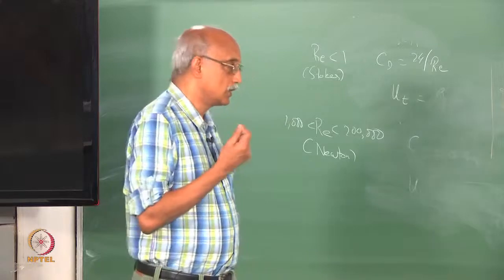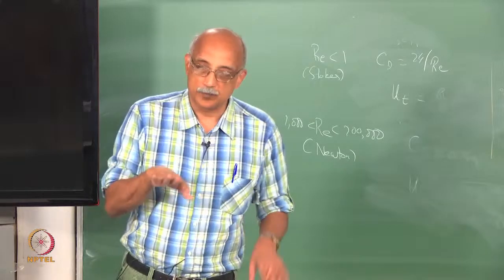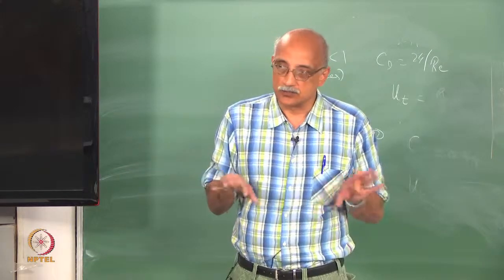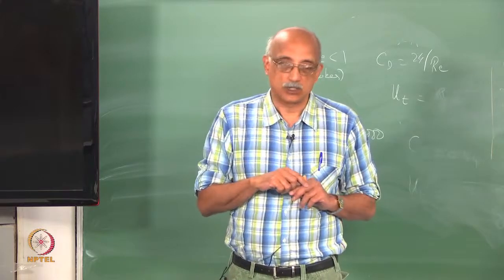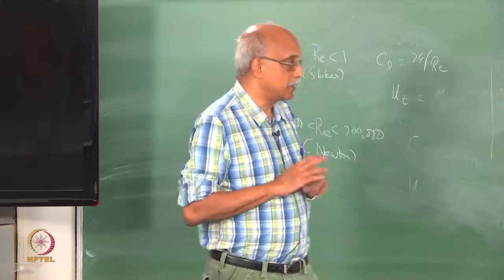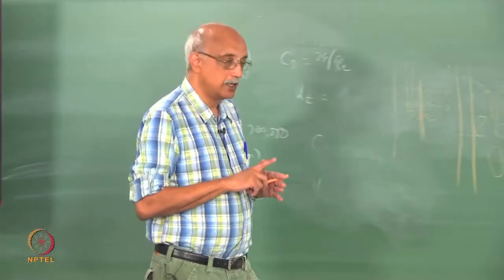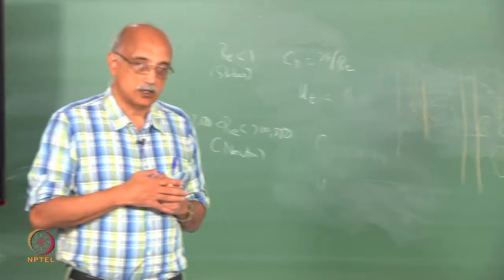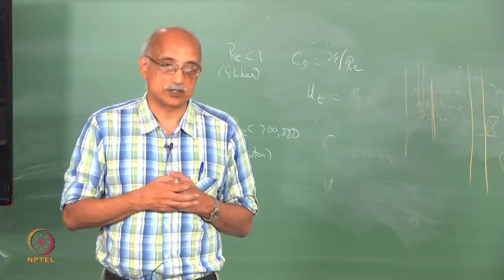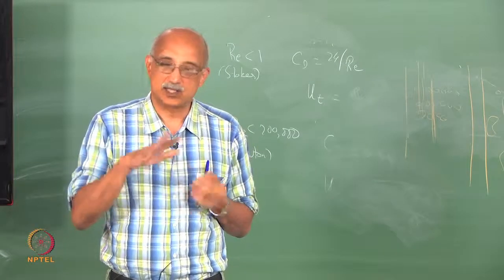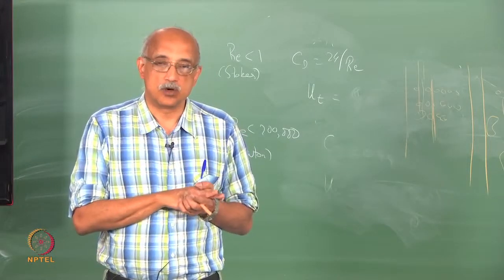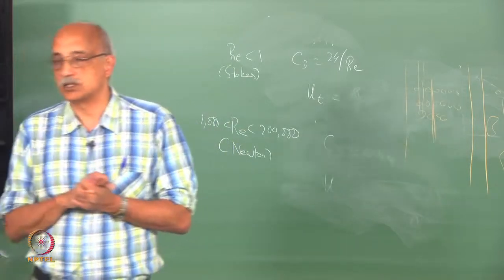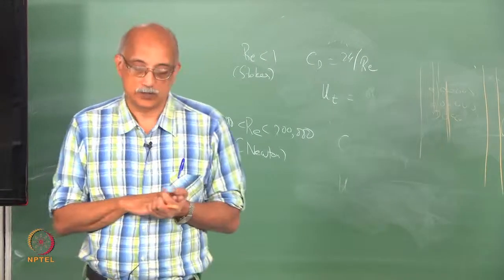So, these are some interesting aspects of operating a packed bed versus a fluidized bed, and the various impacts of particle size and shape and so on. One of the critical parameters in the operation of a fluidized bed is the minimum fluidization velocity. So, in the next class we will talk a little bit about how the minimum fluidization velocity is derived and what is a safe operating point. You know, how far should you be above or below the minimum fluidization point in order to operate your column in the way that you want to.